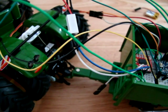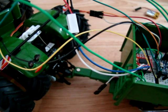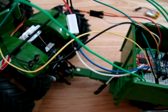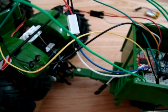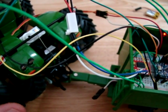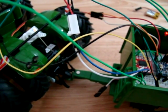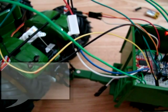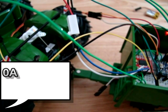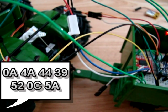Okay, so now we're going to test or set up our link the same way that we've done our steering. So if you open XCTU on your computer again and have your other XBee set up, power this on. So now we're ready to go. Go into your terminal on your XCTU, type in the same command string. Well, the first 5 characters are the same, so it should be 0A, 4A, 44, 39, 52. That's the one for mine.